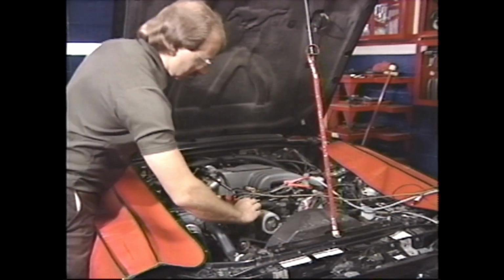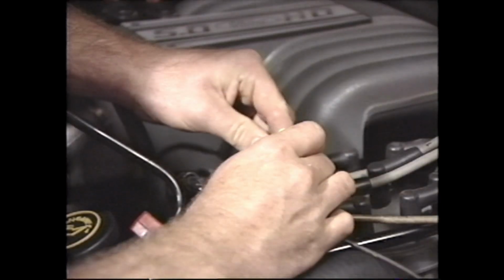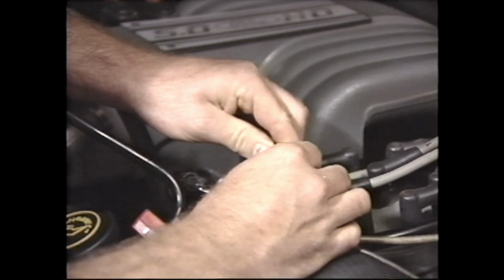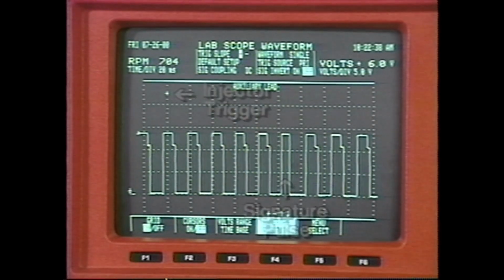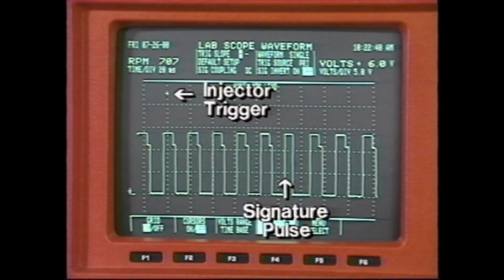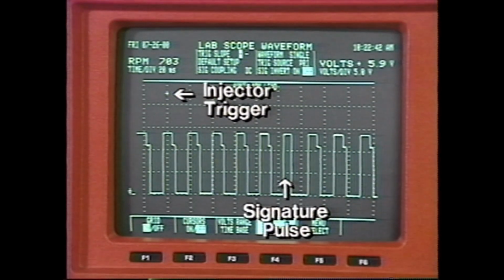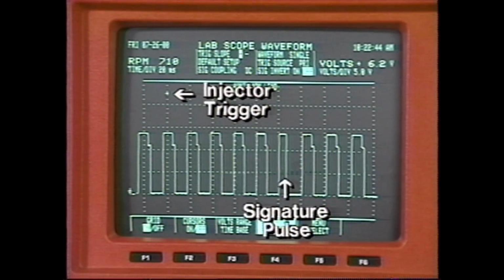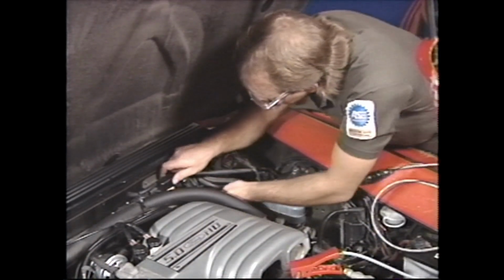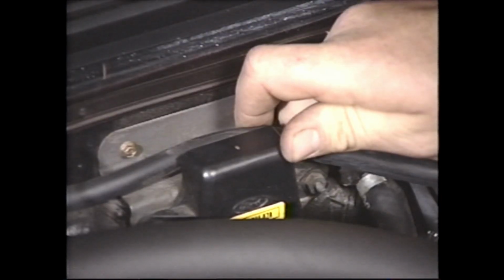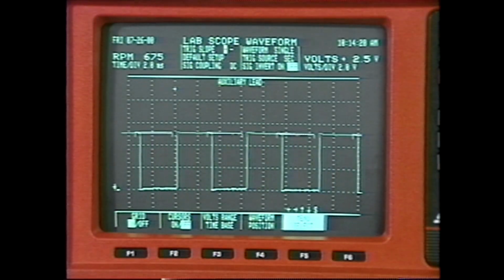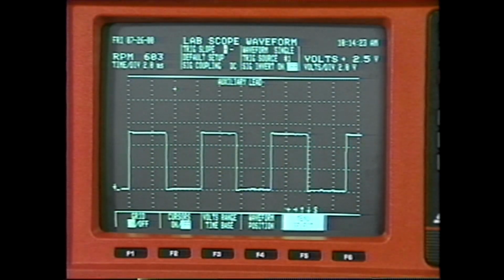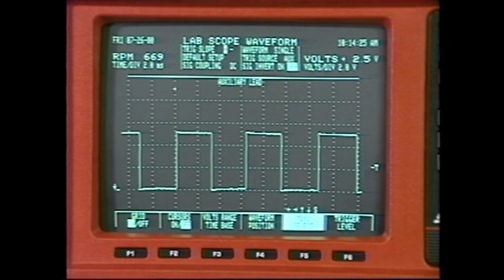Some signals are synchronous to ignition events and should occur constantly while the engine is running. For example, the distributor signals the fuel injection system to start opening injectors when the number 1 cylinder is on its intake stroke. Other signals, like those from a manifold absolute pressure sensor, are asynchronous. These occur only when conditions change enough to provide new information.